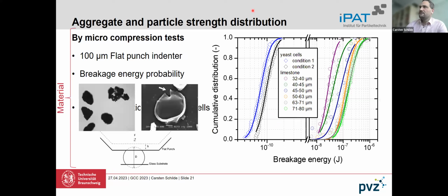Before starting with it, I will also introduce the material function. In our case, we measured our breakage strength with the nanoindentation device. In this case, we don't use the two-roller mill to derive the breakage function, so we calibrate, or fit, the breakage function. It's not the perfect way to go, but that was our approach at this time, and I will show the results in the following.